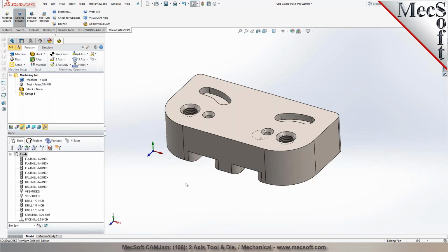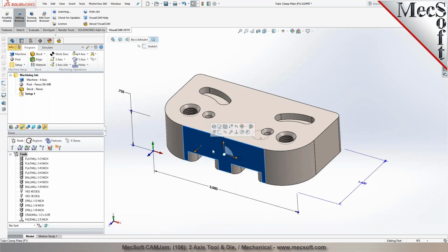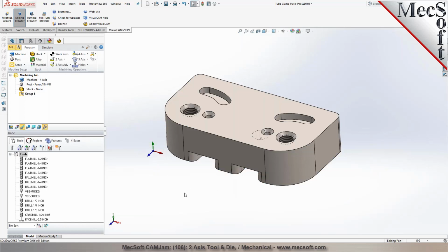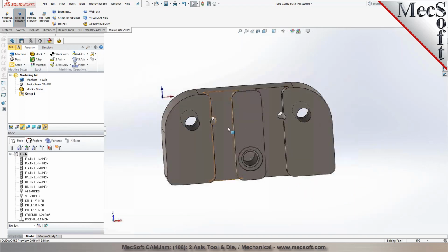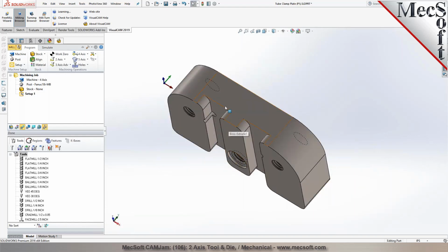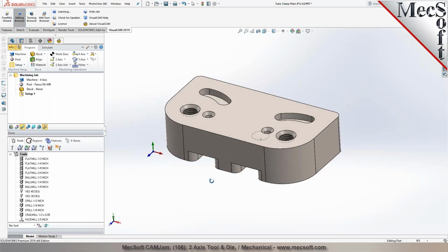So the typical process here is the first thing is we want to establish the coordinate system orientation for machining. If you take a look at this part here, the blue arrow represents the z-axis, the red arrow is the x-axis, and the green arrow represents the y-axis. The way the part is currently oriented here, you would be milling features that are normal to this particular face. That's how the z-axis is pointing, right? So you typically want to either mill from this orientation, the surface that I've selected, with the Z tool coming down from that axis, or you may want to machine the bottom side first, depending on whichever side you want to program first. Am I making sense?